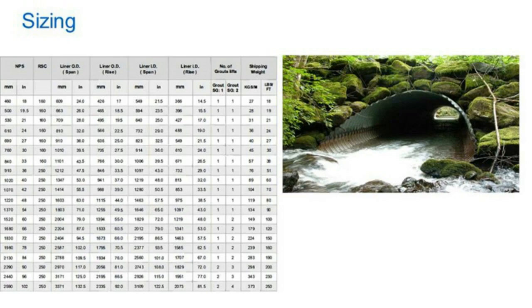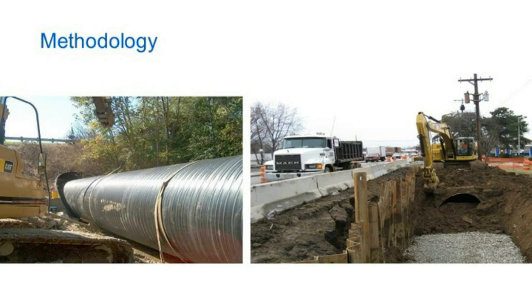As far as methodology is concerned, you need to also decide what methodology you're going to utilize for a successful project. Are you going to push or pull, maybe a combination of both, the new culvert into the host culvert? Are you going to use threaded or welded connection? You need to look at providing a suitable area to complete the necessary joining and installation to ensure that the installation goes on without problems.